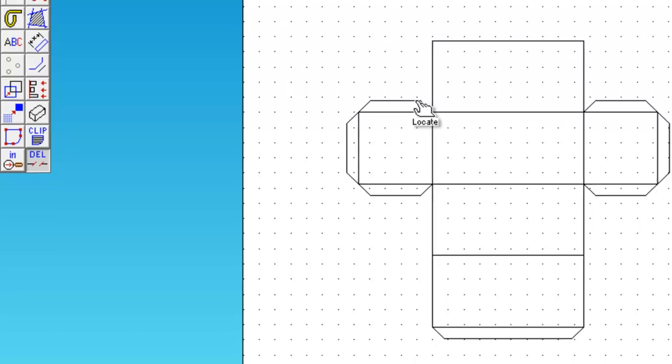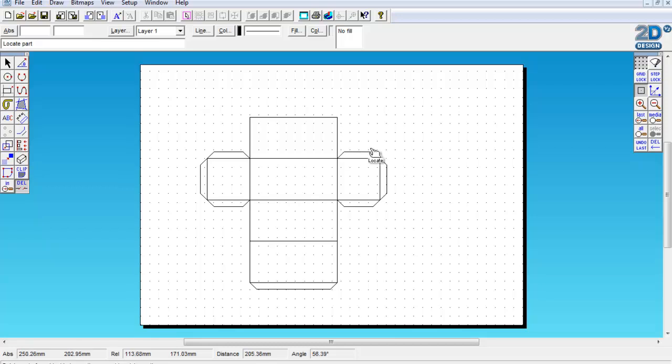And that, when cut out on a laser cutter or vinyl cutter, can be folded into a cuboid net. So now you can see how to use the attach tool and the contour tool to create more specific sizes for your net. The attach tool and the contour tool are two of the most used tools on this software when you're drawing objects correctly.